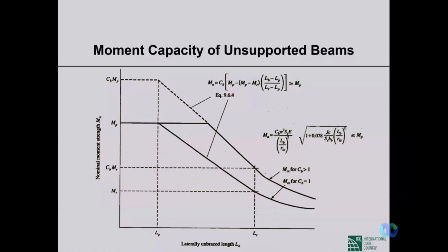So these are the formulas. We have this MCR, which is the formula for lateral torsional buckling that I've shown earlier, and then this is MP, that is plastic moment. We can multiply plastic section modulus with yield stress, and we can get MP.